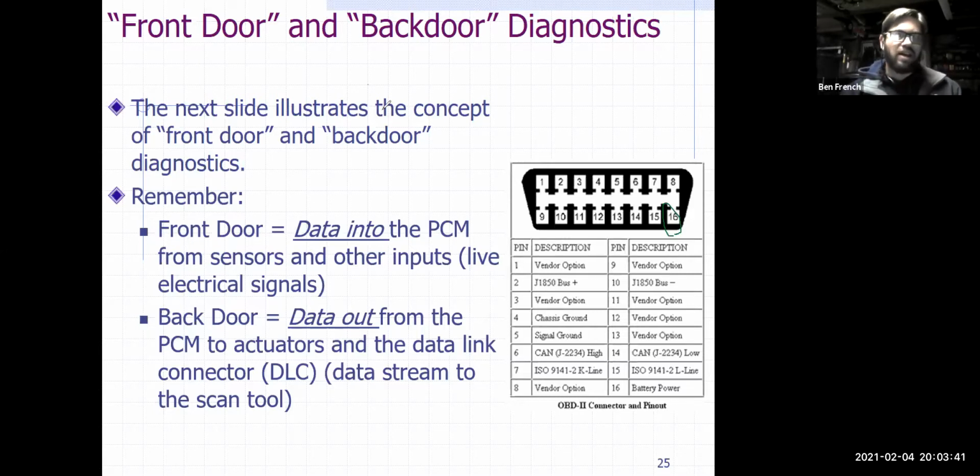Because the problem could be your scan tool. And that's why a typical automotive shop will have like 3 or more different scan tools. And I think even if you become a professional automotive technician, you might buy some $5,000 scan tool at some point in the future. But having this little generic OBD2 interface is still worthwhile, because there might be a time where you hook up that $5,000 scan tool and it doesn't communicate, and you need to see, well, what's going on? Having another tool to plug in there is really helpful. So if you ever have a communication issue, first thing, try a different scan tool.